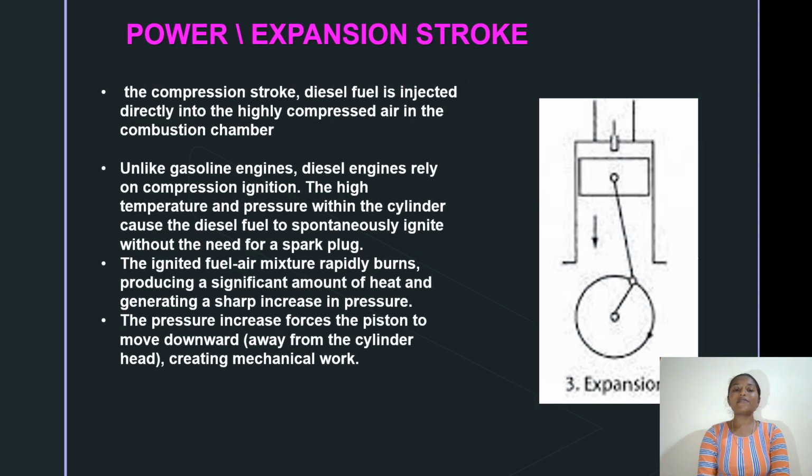Also known as expansion stroke, due to the air being expanded during this stroke. During this stroke, the piston will be at top dead center and moves towards the bottom dead center. Both inlet valve and exhaust valve will be closed. After the completion of compression stroke, the diesel fuel is injected directly into the compressed air in the combustion chamber. The high temperature and the pressure within the cylinder cause the diesel fuel to spontaneously ignite without the need for